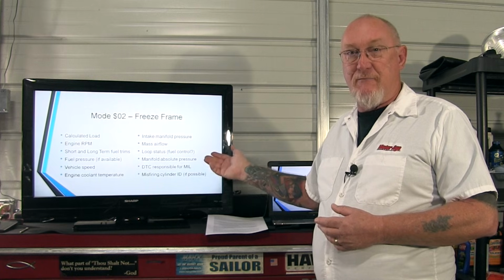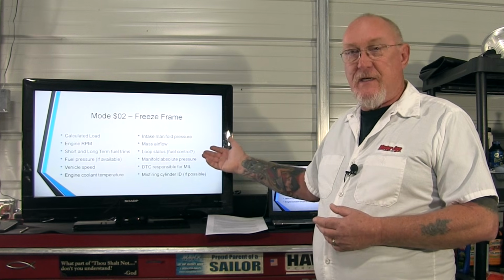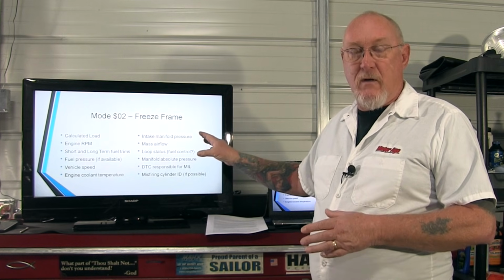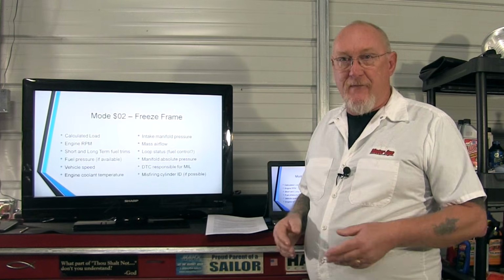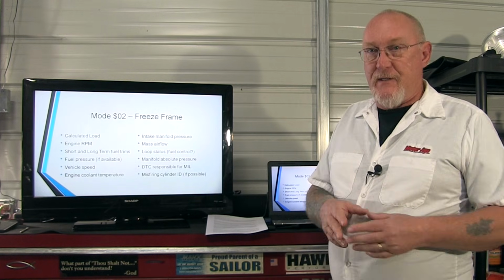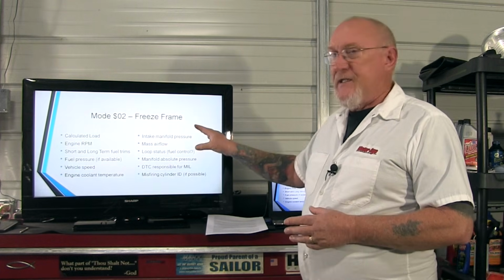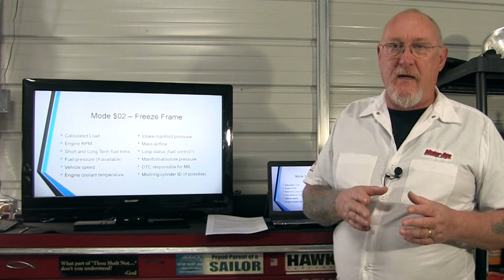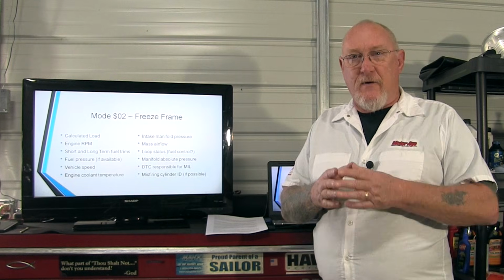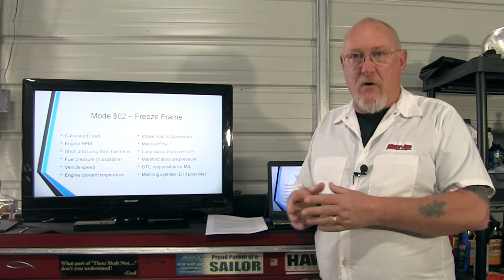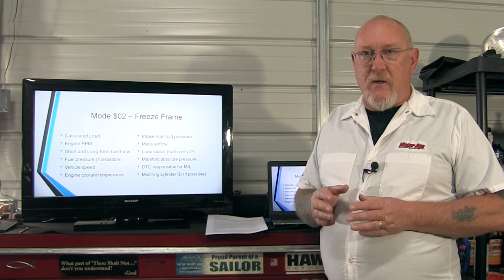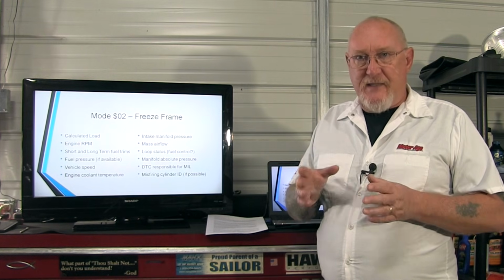It's gotten so much better over the years that you may see a lot more PIDs available to you, and we'll take a look at a few examples when we go to the scan tools themselves. Now, one thing I want to point out here with freeze frame data: freeze frame data is set after the ECM decides to turn on the check engine light. So there might be a small millisecond delay.